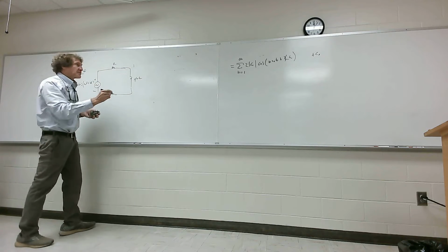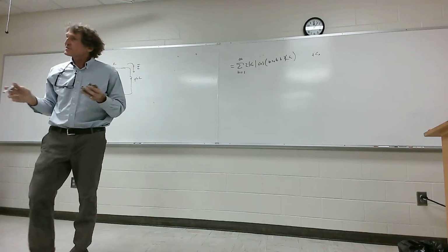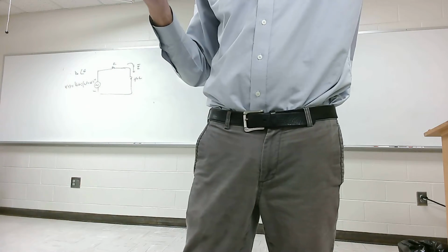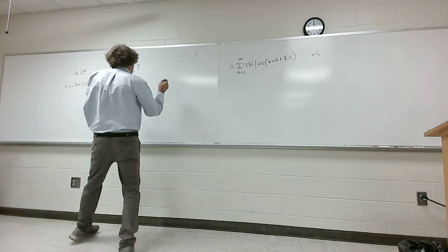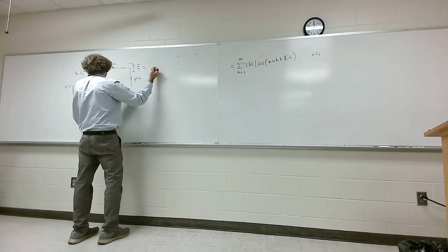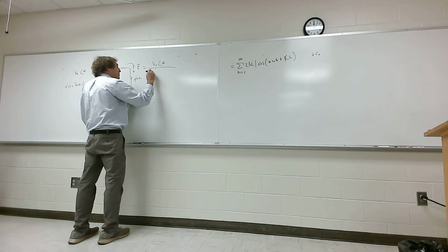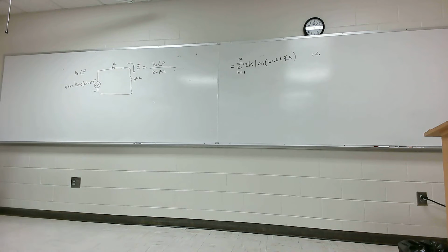Now I get phasor I, right? So how do I get phasor I? Just tell me, own words. I take the voltage divided by the impedance. Y'all with me? So now I'm going to get phasor I, is this voltage, V naught angle of theta, divided by R plus j omega L. Y'all agree with that? Doesn't matter what omega is, doesn't matter what L is.